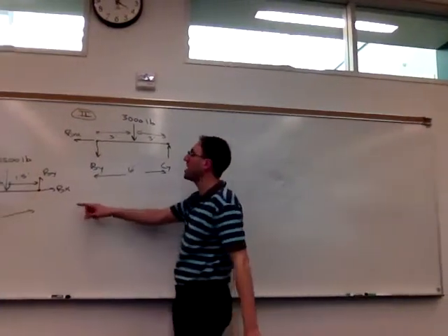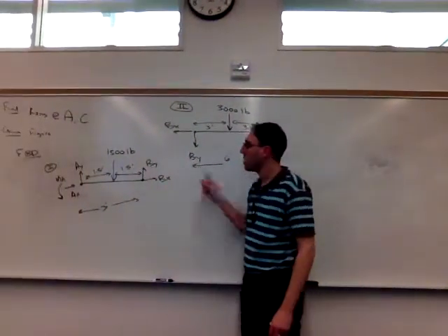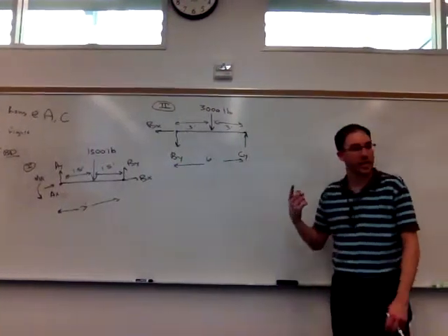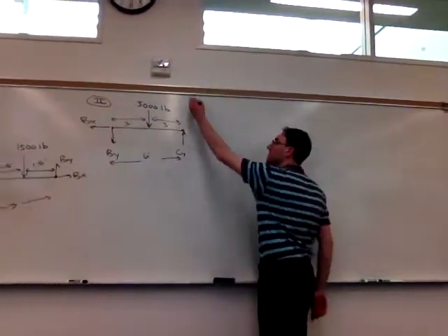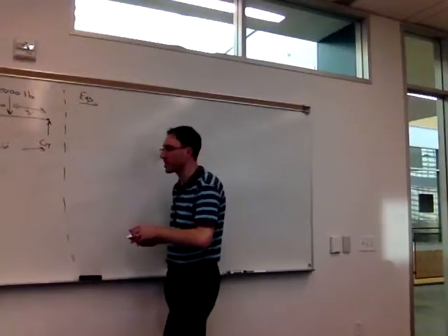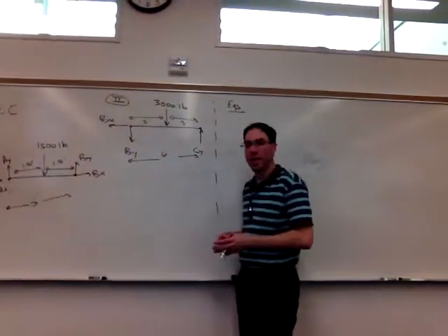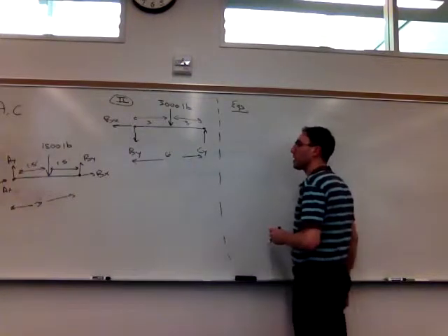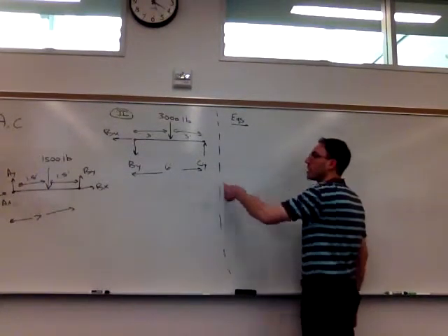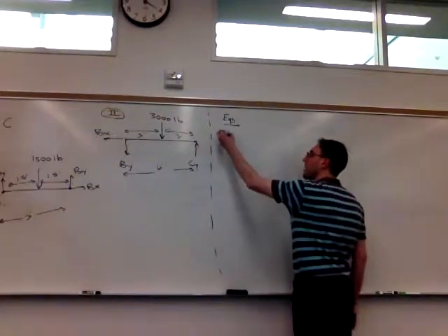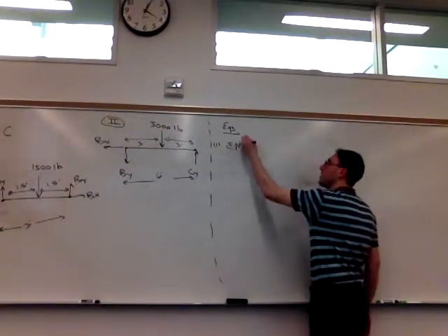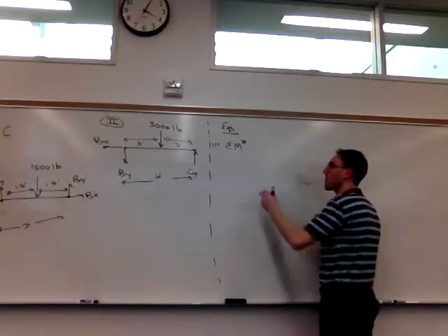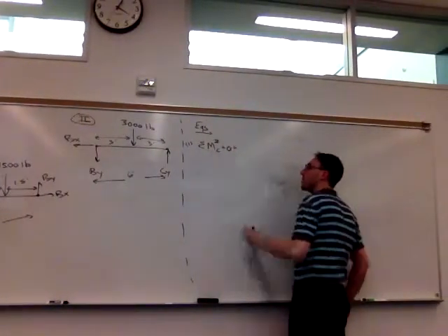Between the two pictures, I now have 6 unknowns and 2 rigid body problems, so I can get 6 equations out of them. So it should be a solvable system. Now it looks just like a Chapter 6 question when we have frames and machines. If we look at free body diagram 2, there's only 3 unknowns in that problem, so that's going to be a better place to start solving this. So I'll start with the sum of moments around C in picture number 2.